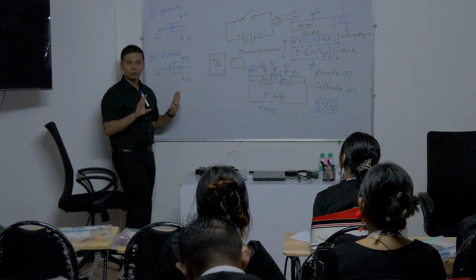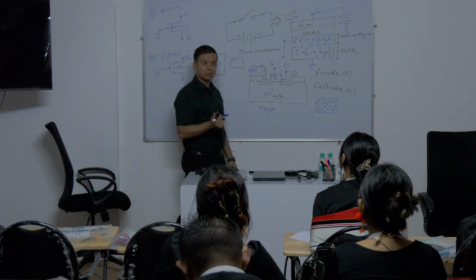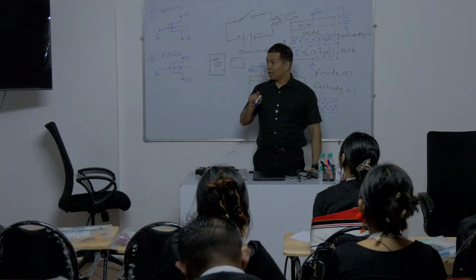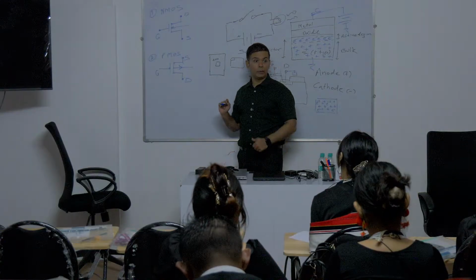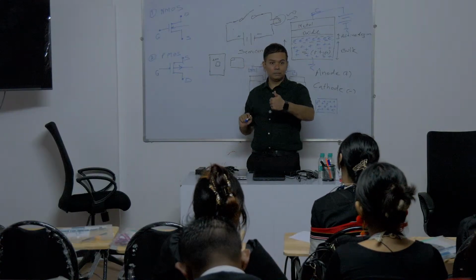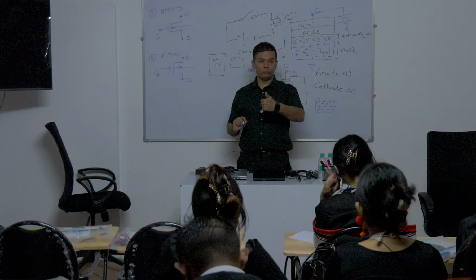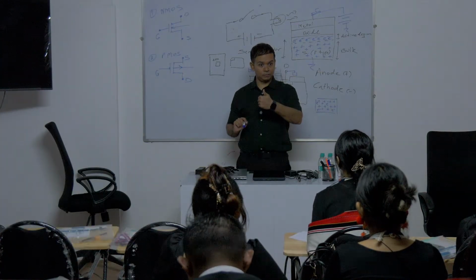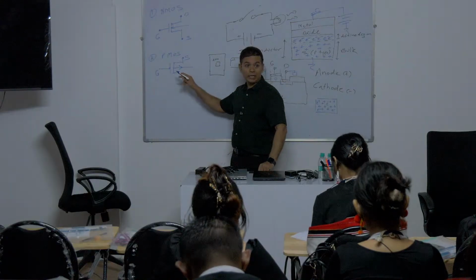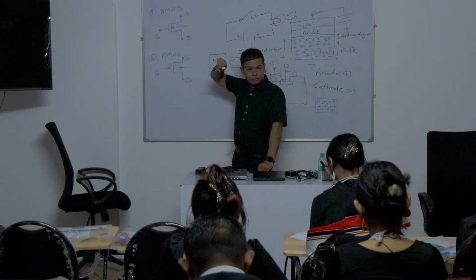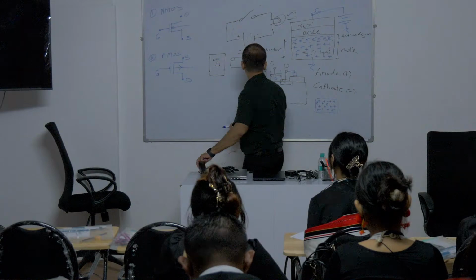So the symbol, you should understand why the symbol is like this. In the other case, which is PMOS, you are bringing what? You are bringing holes. Yes or no? Yes. For P channel MOSFET, you are bringing your holes and the electrons will be pushed downwards. We'll see over here what will happen.